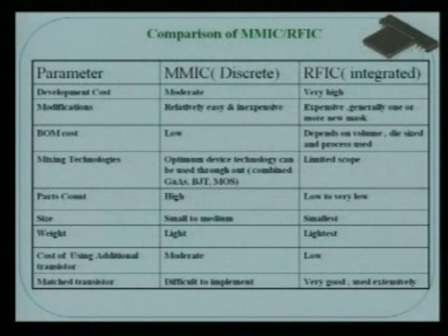So these are the different ranges of sensitivity you want to have. And the more you want to detect the smallest possible signals, the cost of your sensors and your receiver front end becomes higher and higher, because you need a very powerful, highly sensitive LNA. I will talk about the LNA after a few slides.